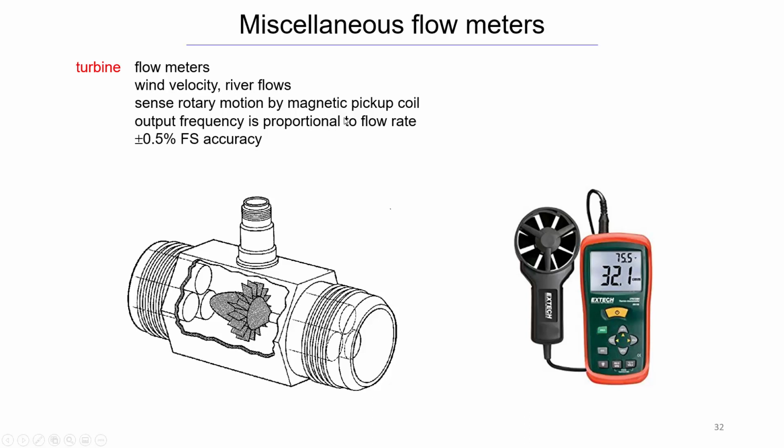I'm not so sure that this semester we got to get into the magnetic pickup coils a whole lot, but say you take a magnet and you have a coil wrapped around it. The magnet creates the magnetic field. And if something metal moves through that magnetic field, it distorts that magnetic field. And that magnetic field distortion ends up resulting in a current produced in the wire.